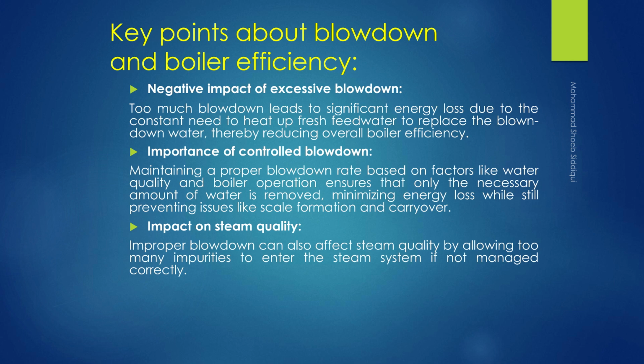Importance of controlled blowdown. Maintaining a proper blowdown rate based on factors like water quality and boiler operation ensures that only the necessary amount of water is removed, minimizing energy loss while still preventing issues like scale formation and carryover. Impact on steam quality. Improper blowdown can also affect steam quality by allowing too many impurities to enter the steam system if not managed correctly.